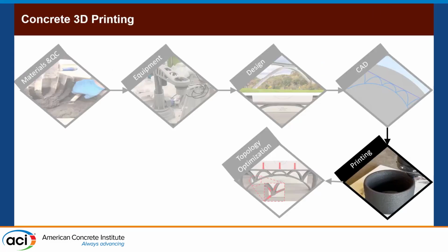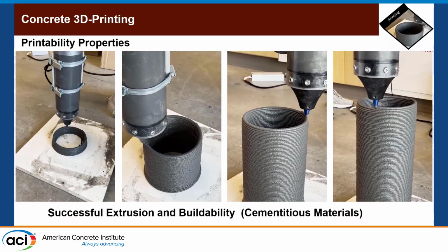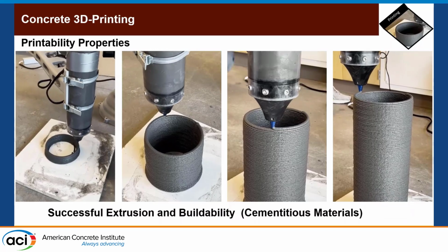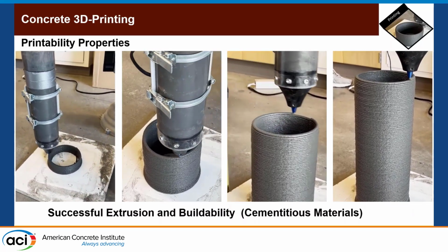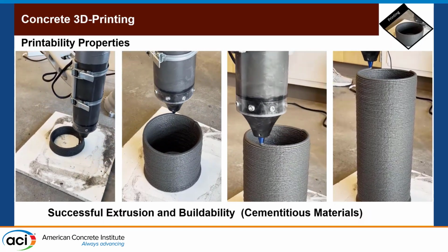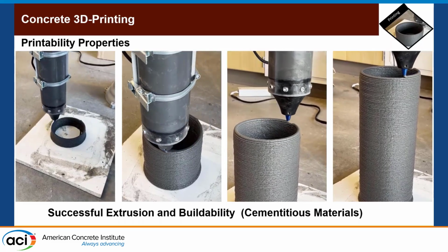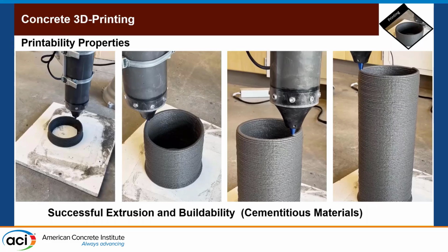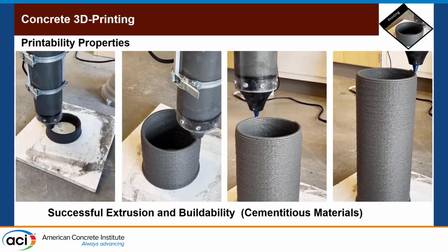we used. So this one is a tube that we printed with a 6 millimeter nozzle. And I'm showing here the first quarter, second quarter, third, and last. And this one was done in 16 minutes. This is not a sped-up print, so every layer was around 7 seconds. The first layer was able to hold around 200 layers.